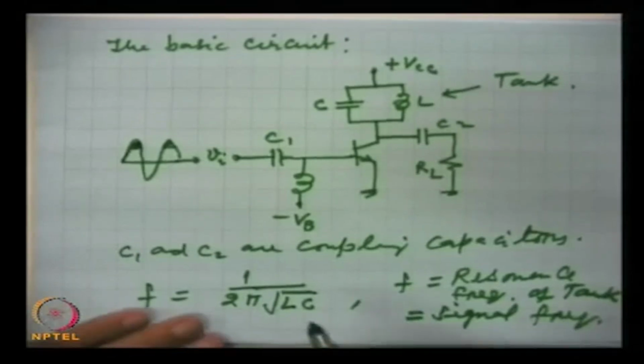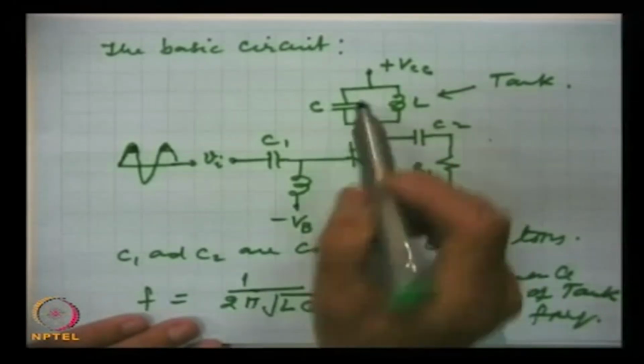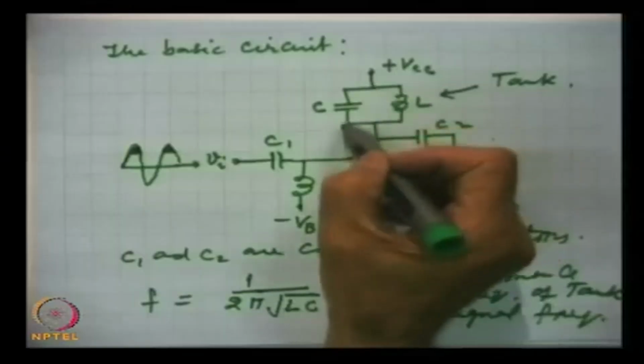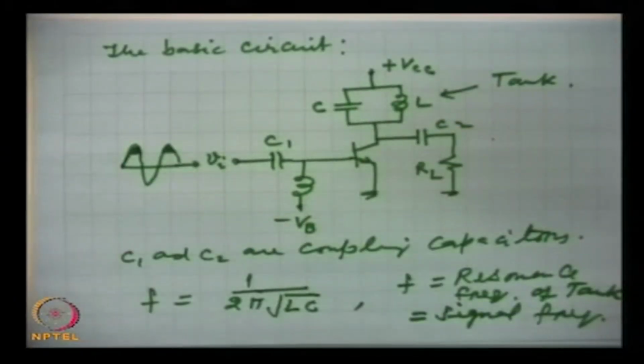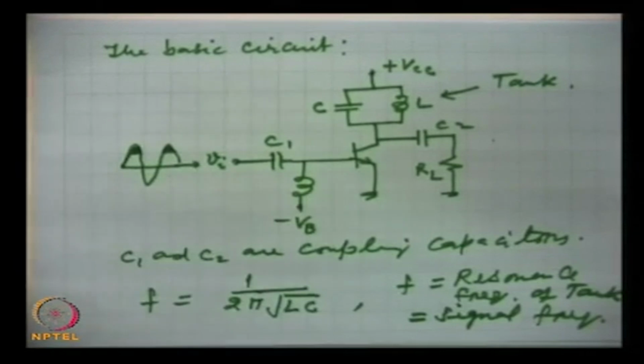and at the output, this tank circuit will get periodic very highly powered collector current pulses. Collector current pulses will be striking this resonant circuit, and I will soon explain that this circuit is capable of converting those pulses into the original, complete sinusoidal signal.